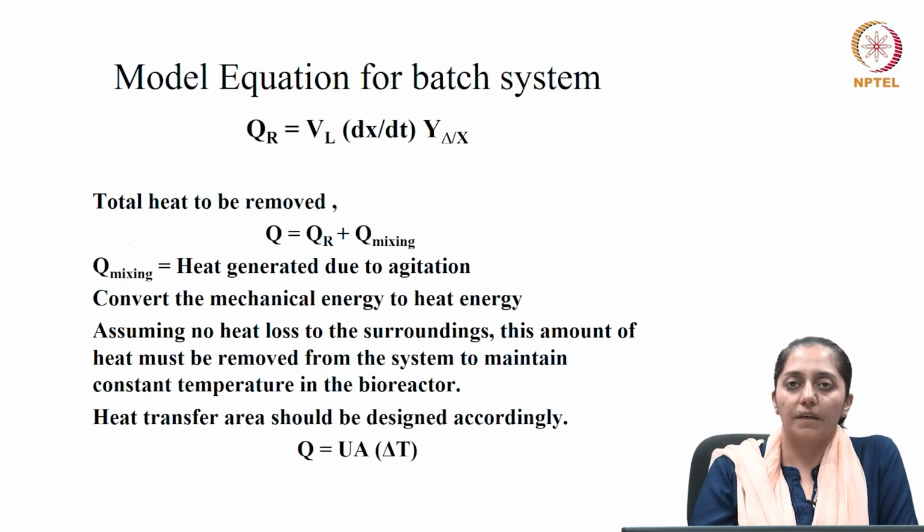Now, if we have to design a cooling system to maintain the temperature of the fermenter at the required temperature, then the heat which is released due to cellular growth and the heat which is generated by the moving parts inside the reactor, especially the impellers, all this heat has to be transferred. So, first we need to understand the total amount of heat which will be generated and which needs to be removed during the fermentation process.